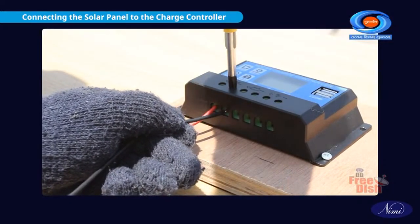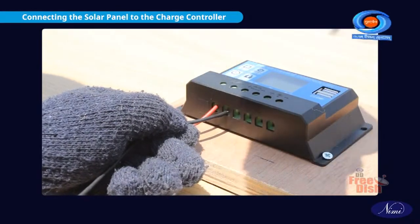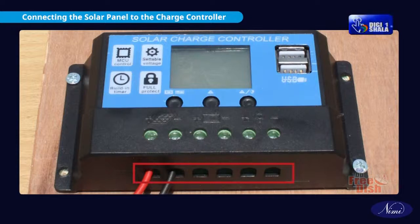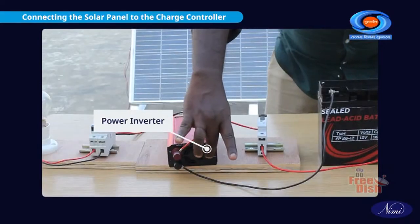Ensure that the connections are secure and tight to prevent them from coming loose over time. Some charge controllers have screw terminals or other connectors to secure the wires in place. Now, switch on the DC circuit breaker and inverter.